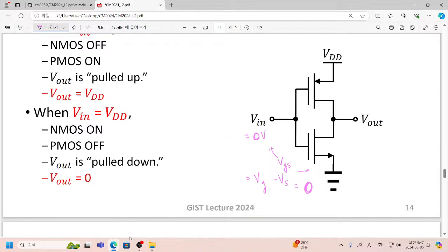Usually our NMOSFET has a positive VT value, since the threshold voltage is intentionally matched to a positive value. So this device is operated in its cutoff region, and it does not conduct any current through the drain terminal.